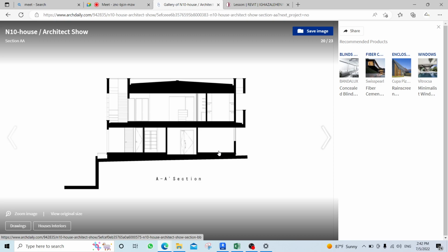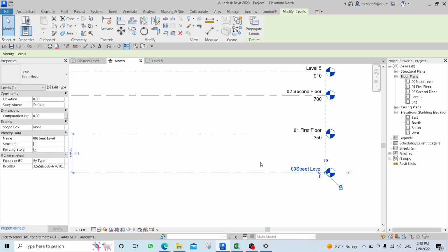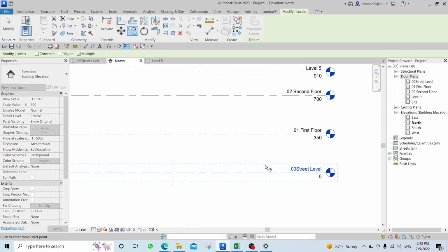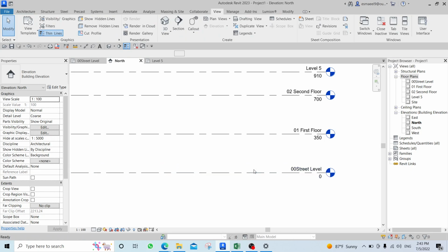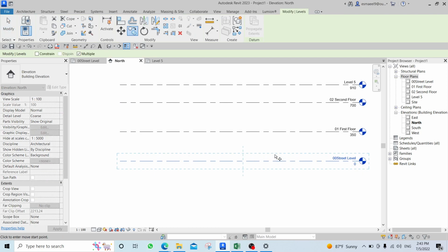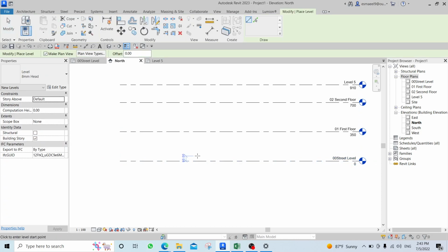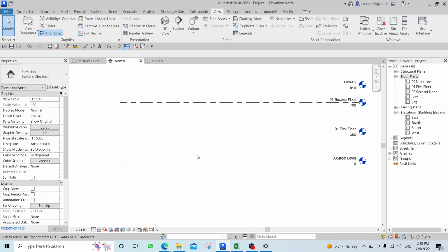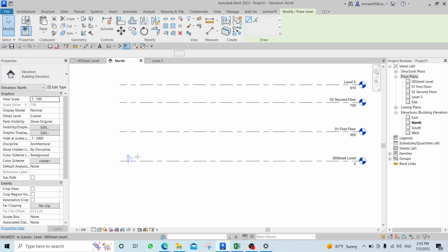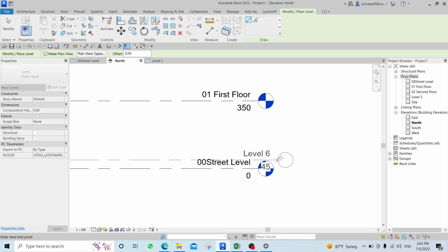So I will have to now create another one, which is CS for create similar, or double L for level. CS, create similar, which is like just clicking double L for levels. So now I want to create a new level, LL. Make sure that it's 45. Bring it to this point.